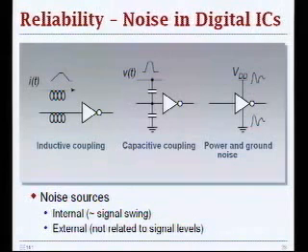There are a number of sources of noise, and just as an example, on this diagram, you can see that if you have 2 lines running in parallel next to each other, then they exhibit inductive coupling and also capacitive coupling. So when a signal on one line changes, that also affects the signal on the other line, and that may affect your voltage at that node.